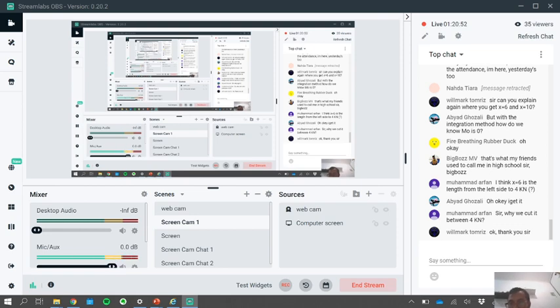Why do we cut it between the 4 kilonewton? Yes, of course we have to, because I already explained just now, right, Muhammad Arfan? Because the 4 kilonewton force makes the equation not continuous, because it's a concentrated force. A concentrated force or concentrated moment will create a discontinuity in our equation. That's why we have to do the cut in between the external concentrated force and external concentrated moment.